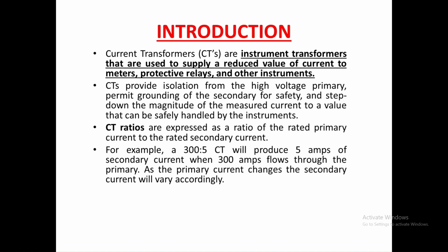CTs are basically instrument transformers that are used to supply a reduced value of current to meters, protective relays, and other instruments. As we know, in large power systems, a high value of current is flowing in the conductors, so that cannot be measured through energy meters.